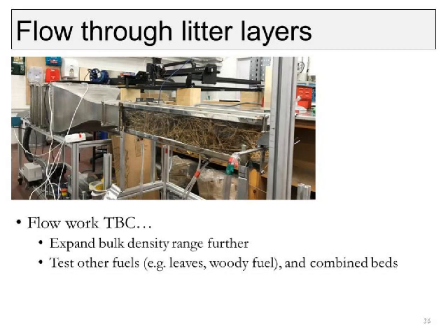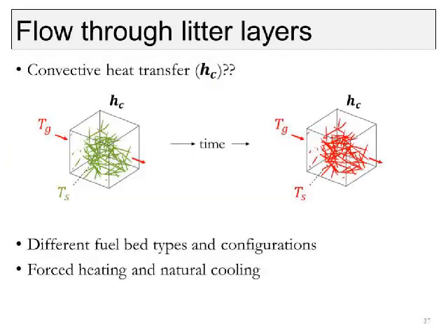But then we want to go this step further and also look at the convective heating. So if we put our fuel into the test section and we force through high temperature flow, well, that's going to raise the temperature of our fuel as we would expect, and that process should be driven with some convective heat transfer coefficient. We should be able to use that to describe what's happening. But this is a case similar to the drag force and the drag coefficient, where we've used some rough approximation. We're not really sure how good it is. So the goal is to, again, try to do some simulations, some experiments, and see if we need to and if we can improve what we use for our convective heating model.